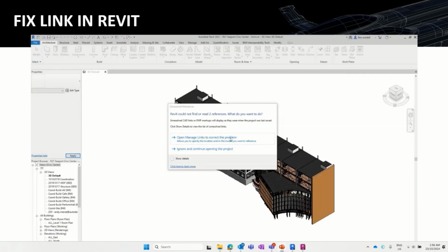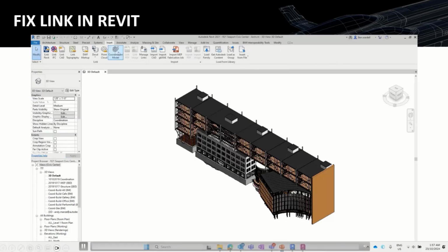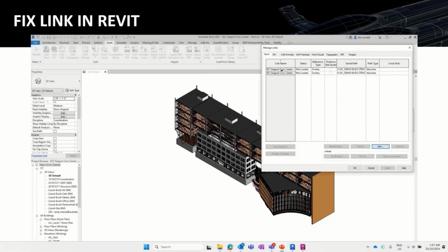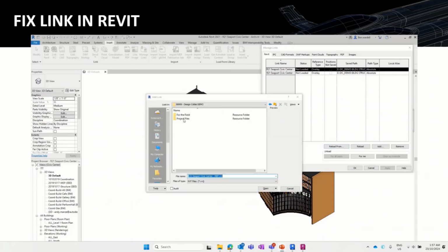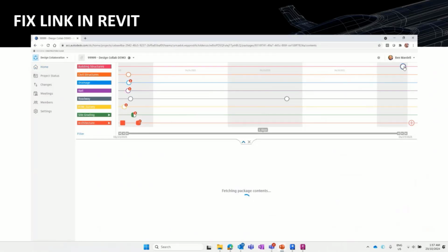Let's say, for example, you are working with the architects model, and you can always have the latest file from structure or from mechanical or from plumbing, and you can use Manage Links to link the model on top of your building, so you can see it, or you can rearrange the coordinates according to the shared point file from Civil 3D just now.